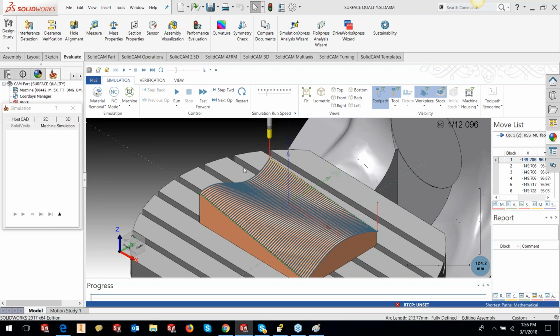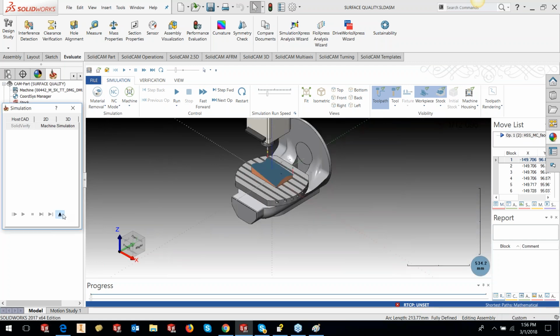So it's very important that whenever you use the distance function, please use the synchronize points button to get the points synchronized on every pass of the toolpath. Okay, so basically today we are going to end it here.